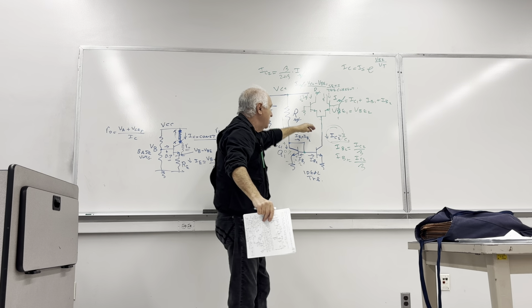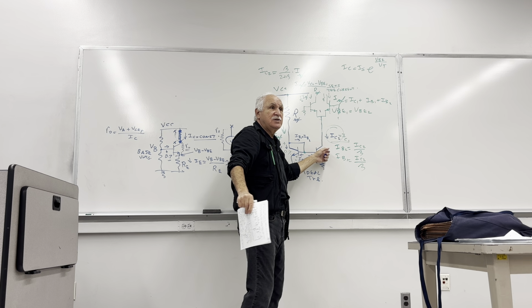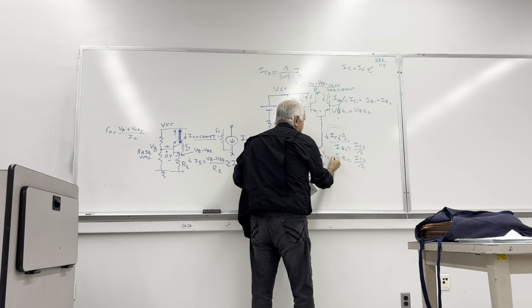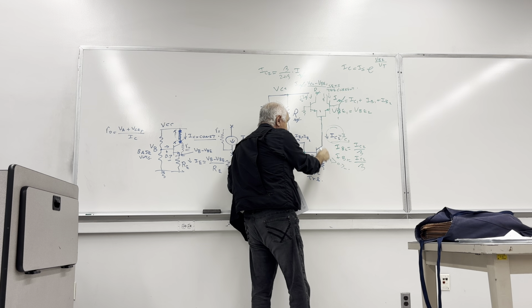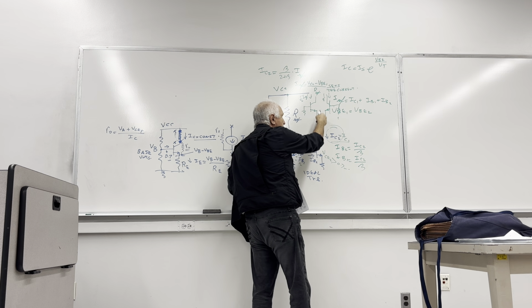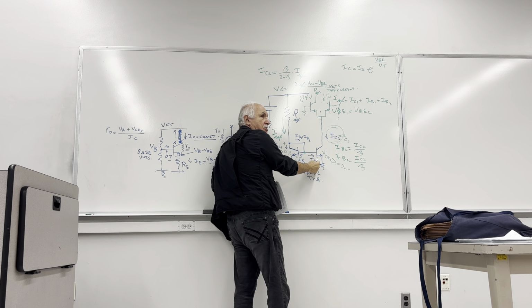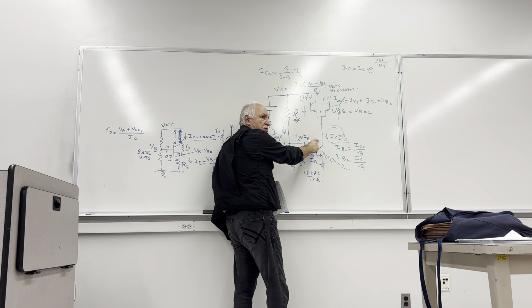It's a constant current, as long as you haven't saturated that stage. You know what that means? This VCE2 is greater than 0.7. You've got to make sure. If this sinks below, like nearly 0.1 of a volt, you're not going to get current here. If this goes to 0.1, and this is a 0, already this transistor goes into its saturation region.